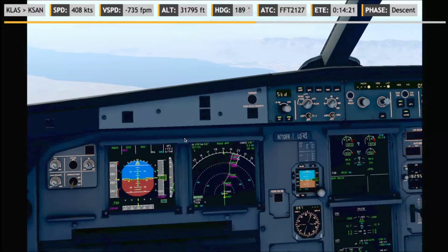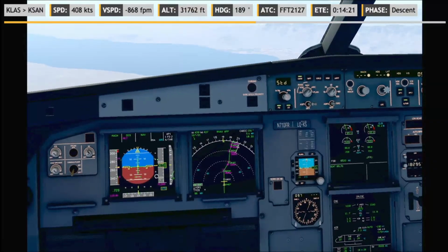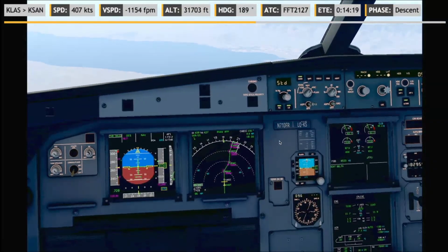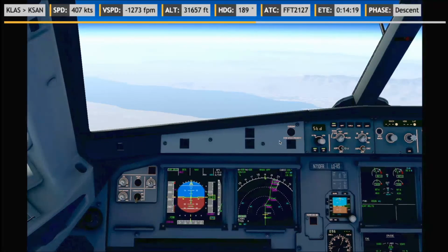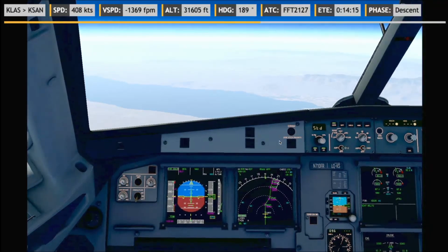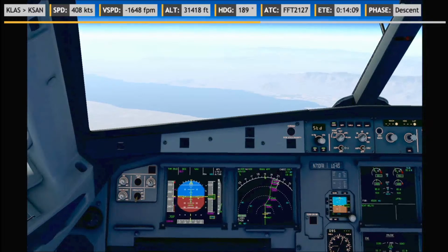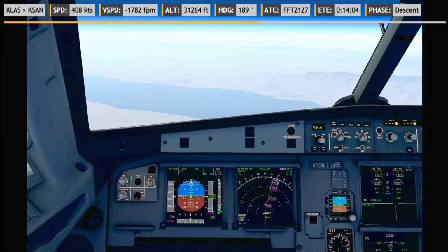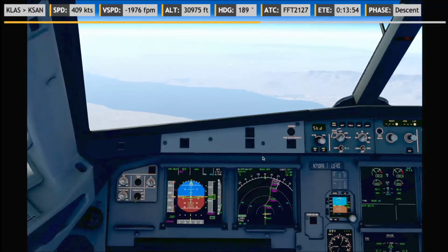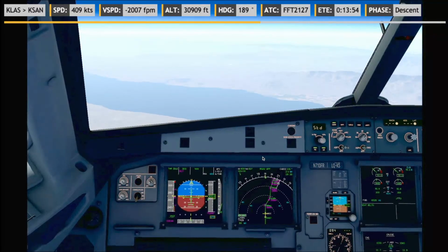Okay, there it is, our glide coming in. It's all pretty similar content, except the destinations are different and the procedures might be a bit different. I think this is the first non-precision approach we've done on the channel, or we are going to do on the channel. Okay, thrust idle. It's indicating there, and we have 240 as our first restriction at Momar, which is our next waypoint. Okay, it's indicating RNAV approach, and let's go through our checklist.